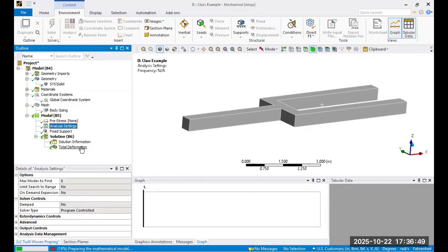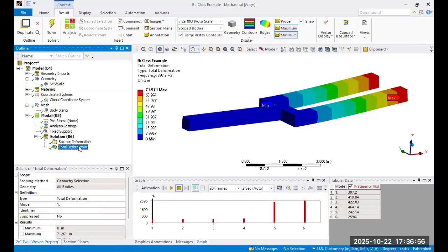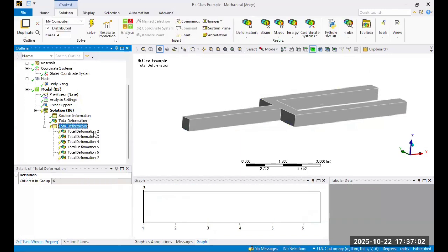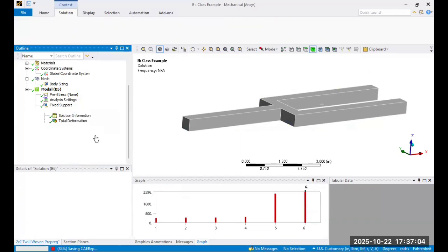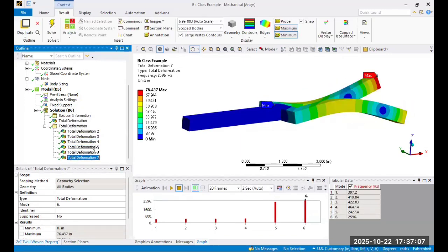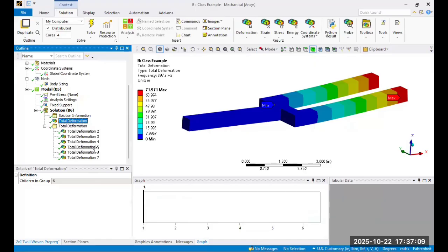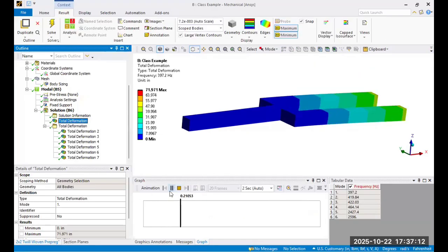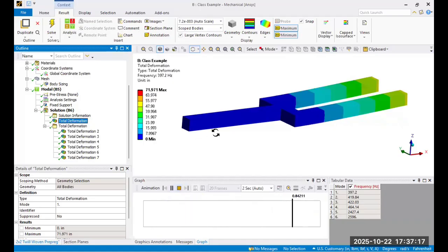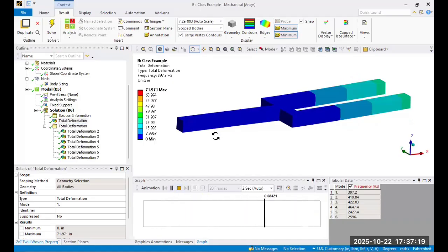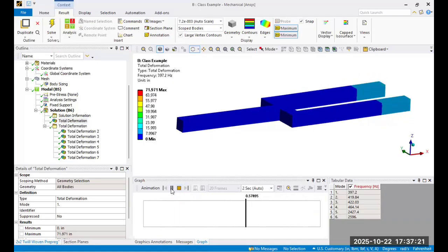Okay, I don't know why that broke. Okay, weird. But yeah, you can click create results at all sets here. What this does is now I can evaluate all results. This gives me all the different shapes, and I can just go through them. So let's go through them and see what they look like. This is the first mode shape. What kind of mode shape is this? Any thoughts? Bending, right? It's pretty clear, we're holding the tuning fork at the end, and this is one of the mode shapes, the bending shape.